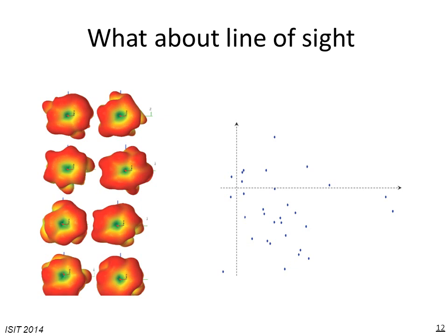The question may come up: what happens if we have line of sight? Here I have an example of another constellation realization in which the same antenna that I introduced before has been switched, but the transmission is line of sight. There is no reflection from the environment. And as you see, the propagations around the transmitter, which are the reflections of signals in those on or off mirrors, will create enough richness in the channel that effectively you get the same distribution of the constellation points.